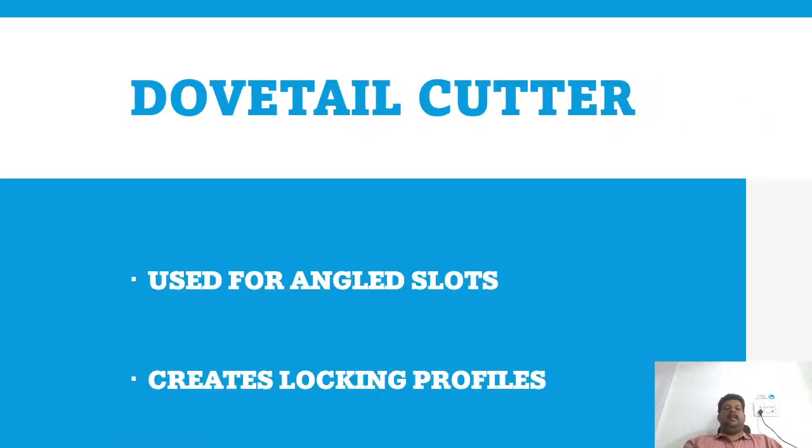Now, let's move on to another very important tool, the dovetail cutter. This dovetail cutter is used to create angled slots. Unlike normal slots, this is not straight. Both sides are cut at an angle, forming a shape approximately like a V.